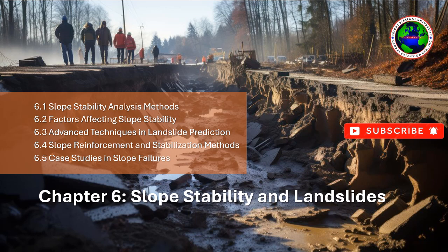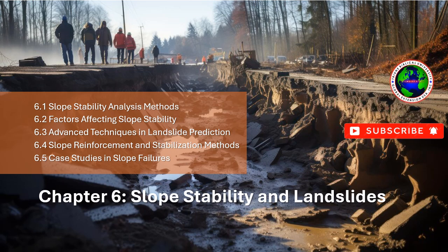6.1.3 Finite Difference Method, FDM. The finite difference method, FDM, is another numerical technique for analyzing slope stability that divides the slope into a grid of nodes, solving the differential equations that govern the equilibrium conditions for each node in the system.